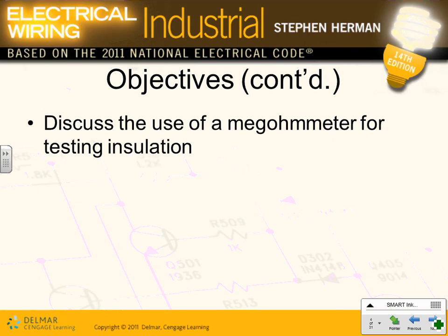When you become a project manager, if you're an electrical designer, guys, you will never hear this. If you're a project manager, you're going to hear the term megohmmeter. When you install the electrical system, before you energize it and blow up half of the building and get sued and get fired, you would hope that somebody will measure all these feeders. So what they do, guys, is they measure the feeders. You measure the installation of all of them, especially the feeders, at least the feeders.